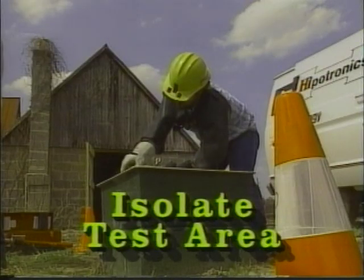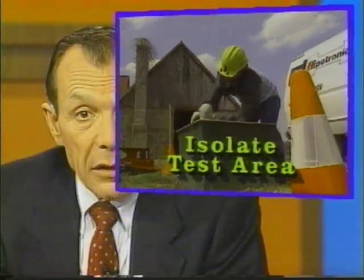The isolation of the test area must be complete enough to ensure nothing can enter the area except for the personnel who have been trained to work live cables. High voltage test equipment, barricades, signs, and operating personnel are some of the methods used to isolate the area.